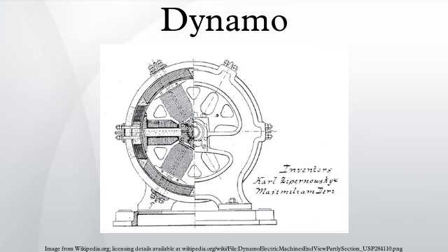The field coils of the stator were originally separately excited by a separate, smaller, dynamo or magneto. An important development by Wilde and Siemens was the discovery that a dynamo could also bootstrap itself to be self-excited, using current generated by the dynamo itself. This allowed the growth of a much more powerful field, thus far greater output power.